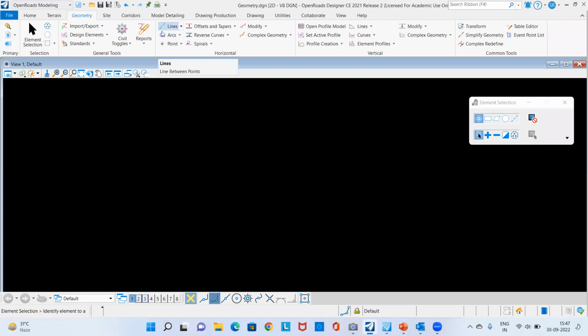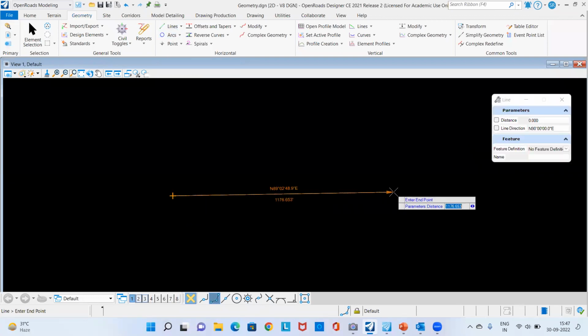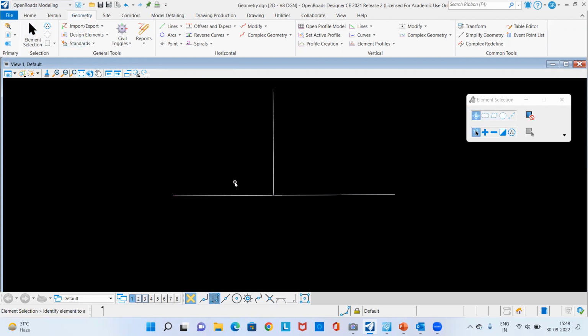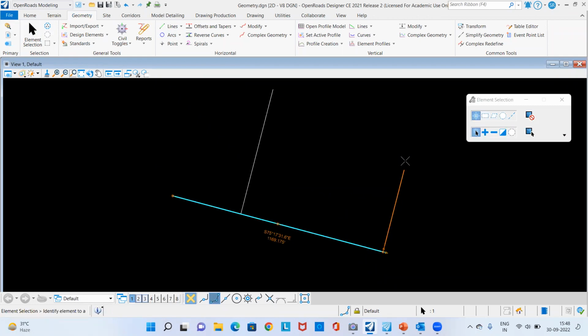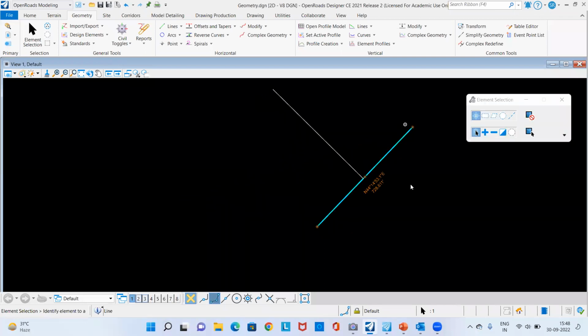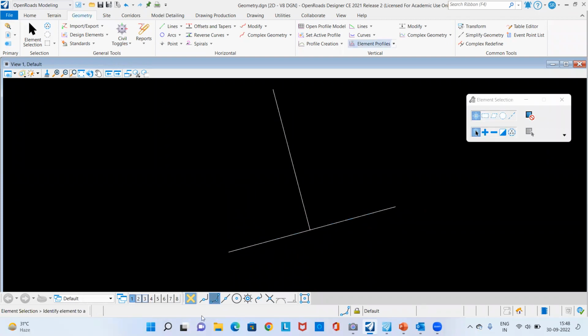And let's see how dynamic a relationship it maintains. So I'm creating a line here. Second line, I'm creating perpendicular to this first line. Okay. So now these two lines remember how they are created. They remember the relationship. So let's see. When I change the location or orientation, the second line always maintains that perpendicular relationship with this line, like that. So these are smart objects.